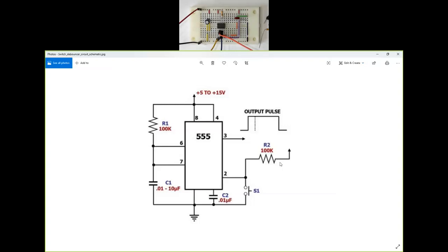And the blue stripe has been connected to ground externally to keep the number of connections onto the proto board to a limited number. I also need to give it two more things: ground and VCC. So the bottom rail is connected to black, connected to ground of the Analog Discovery. The top rail is connected to the red wire of the Analog Discovery to give it 5 volts. I believe I've made all the connections here. So let's go ahead and bring up waveforms.